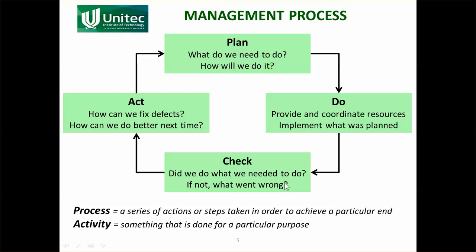And you check. So as you're doing the work, and at the end of the work, you make sure, are we actually achieving our objectives? Are we bringing it in on time? Are we actually doing what we're required to do? So if we're doing concrete, for example, you'll be checking to make sure, have we got the right type of concrete here? Is the steel properly spaced? All those sorts of things there.